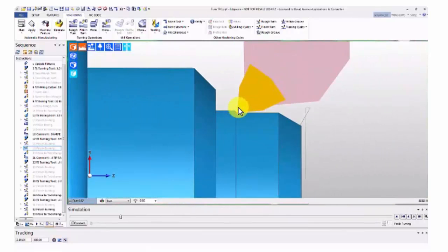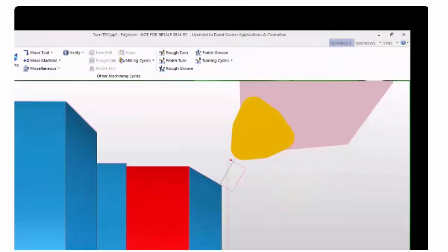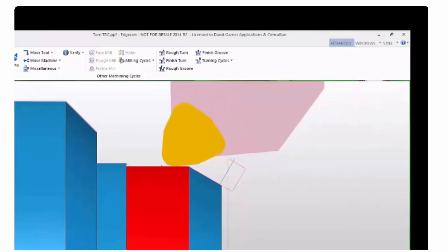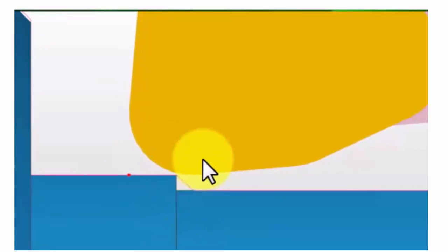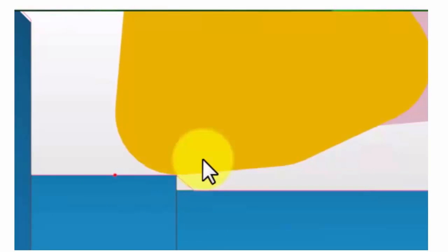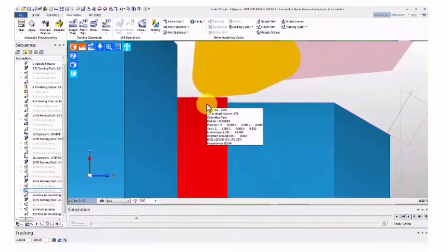But if you put this in with a bigger tool, if we send that around there, when it gets to this corner, how on earth is it going to go up that line there? It's not possible because we've got this massive rad. It can't possibly go up there. Now from the point of view of this system, because it is a CAD-CAM system, it will actually give me a program that makes sense because it will work it out.